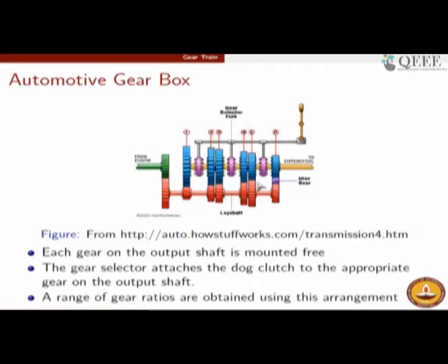But now if you want to reverse the gear, it is not possible to do it with one gear pair. If you put an idler gear in between this piece of red and blue gear, then you will achieve the condition that the blue gear is rotating in the opposite sense. I will show that to you here.